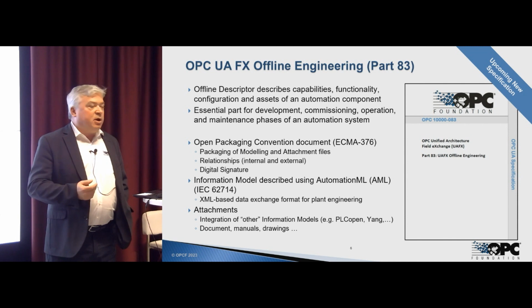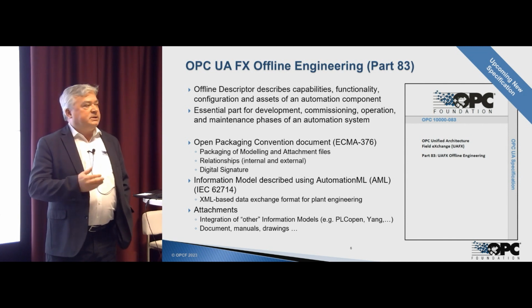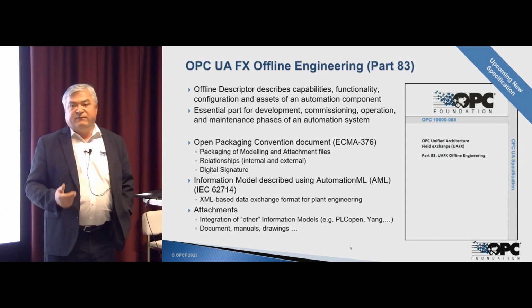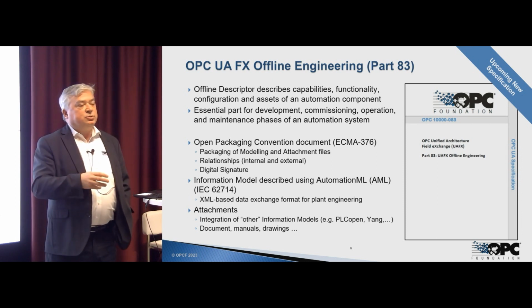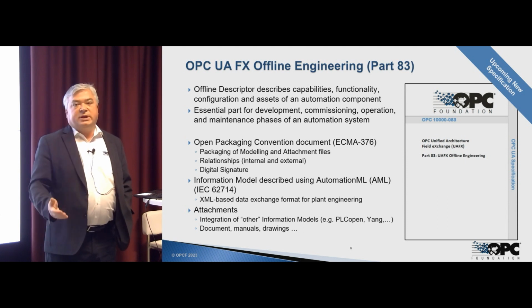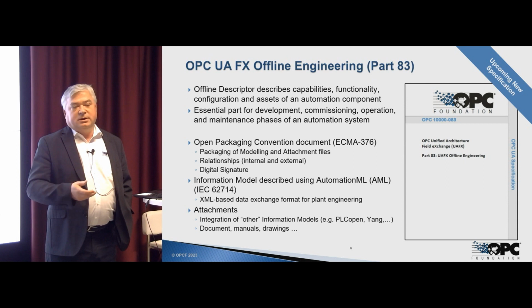We call it the offline descriptor, which contains all the capabilities, the features, or also constraints of a controller in the first step, but then later also for all the field devices. And this descriptor is being exchanged between stakeholders to actually plan a project without the real devices, but then at the time of commissioning, you deploy a certain configuration to make then the real operational, let's say, application.